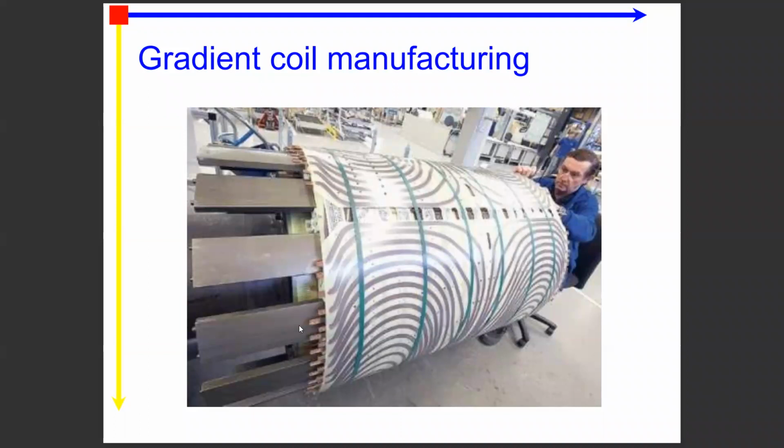And you have to, of course, minimize those forces. You have to optimize the current distribution and optimize the temperature flow, using temperature calculations in simulation tools. And you have to check for outside fields to be minimal, inside fields to be uniform. You can imagine it's a lot of things to optimize in one go. And so you have to have a very large objective function, which takes into account everything you are trying to achieve.